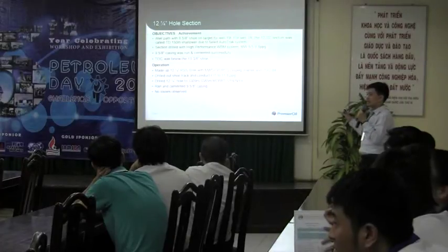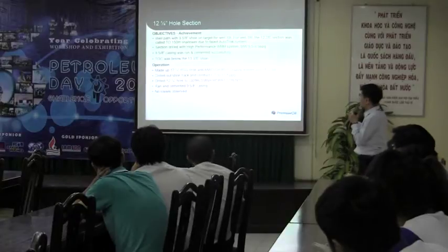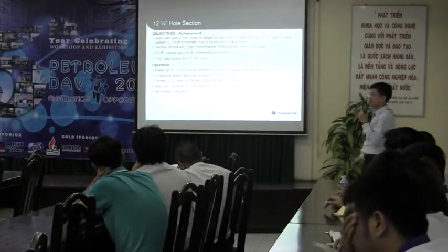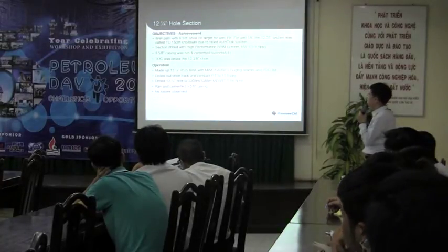The second is the same. We make up the 12-inch BHA, a directional BHA, with MWD, gamma ray, resistivity, Doppler, and a PDC bit.